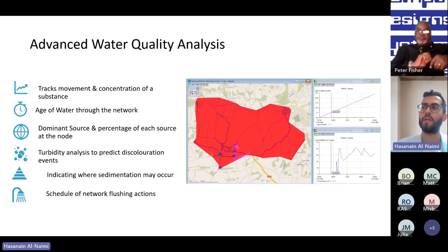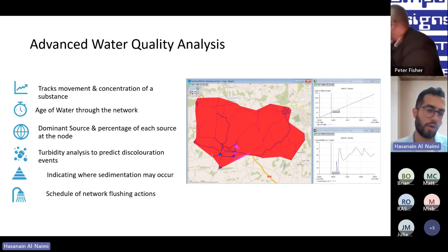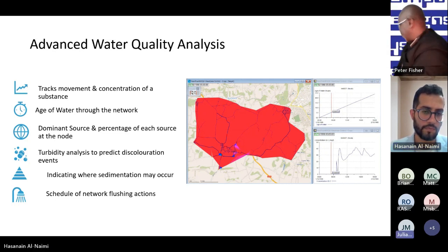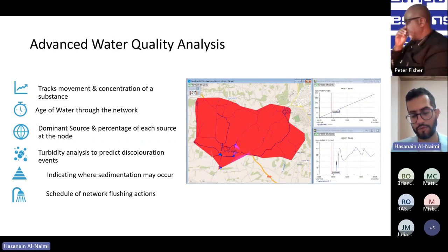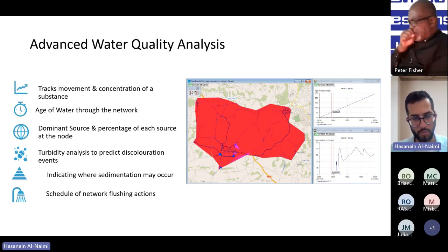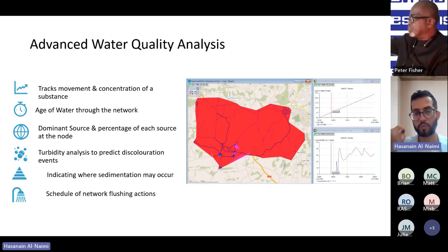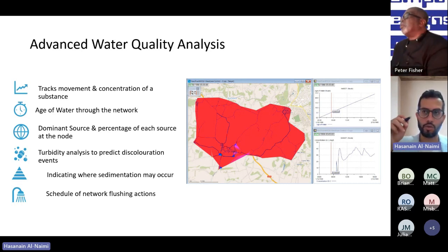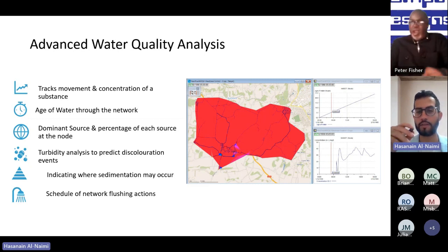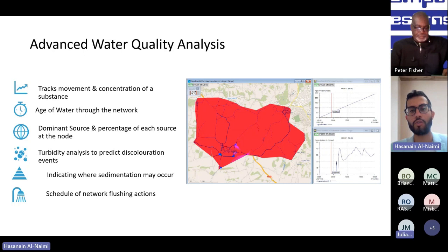Right, yeah, I get you. So you're speaking about GIS or SCADA or both? You're speaking about both, yeah? Yes. So let's take the example of GIS. Let's say you already have some data in GIS, but that GIS model was updated. When you come and import that into Infoworks WS Pro, the software will tell you that there are some changes, and it will ask whether you want to overwrite them, keep them separately, or add to what you currently have. So you're going to be choosing in Infoworks WS Pro what you need to add as extra data.